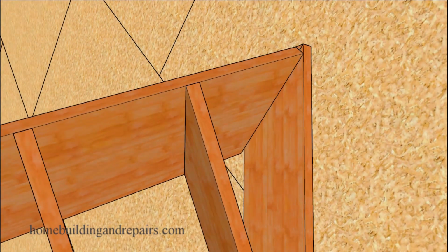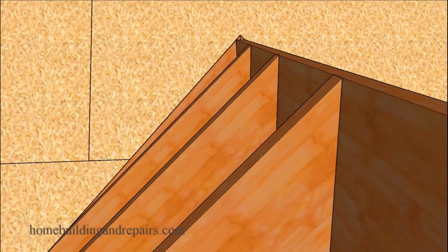Next up, let's go ahead and head over to the other side. Give you an idea how the sheathing is going to kind of connect into here, run straight on through. And since this is a 45-degree angle, you could always shape the top of the ridge.